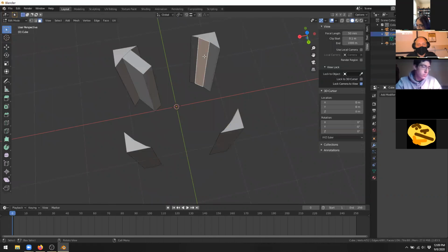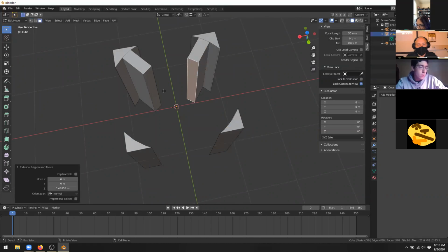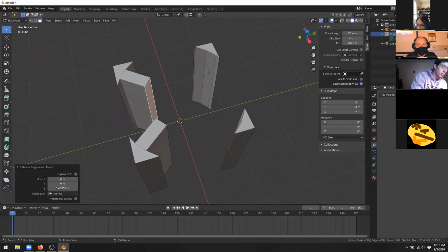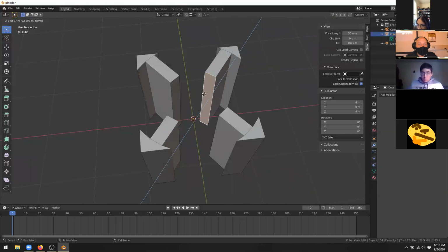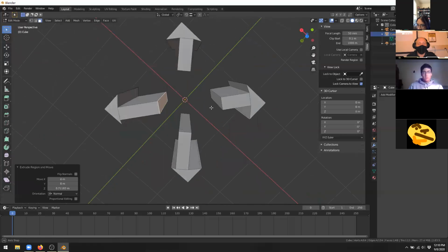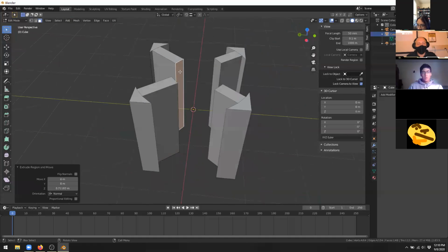So I can go in and I could extrude these middle pieces here if I wanted. I couldn't do that if I still hadn't applied the modifier, because it would still technically be a cube and a cylinder versus the end result of those two things subtracting from one another. So pros and cons to either direction with things. Does that make sense? Modifiers, or at least one modifier anyway.